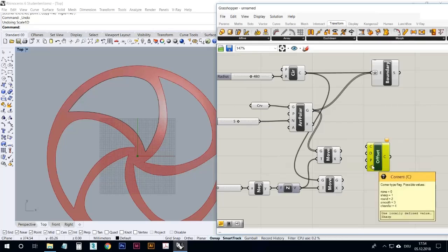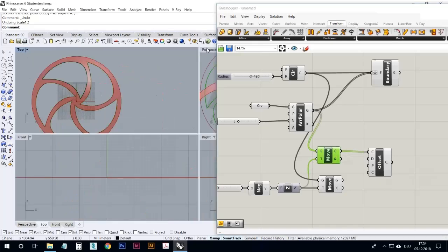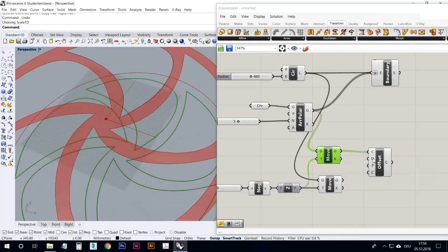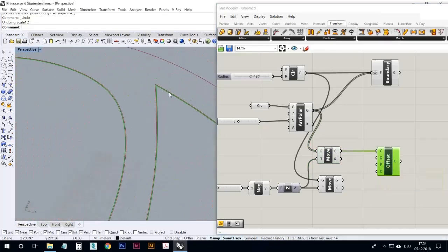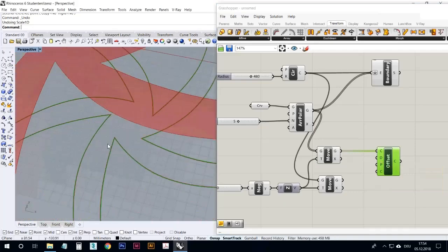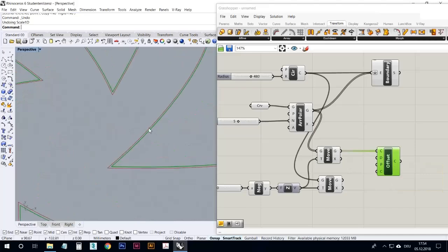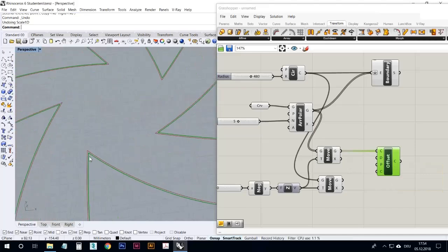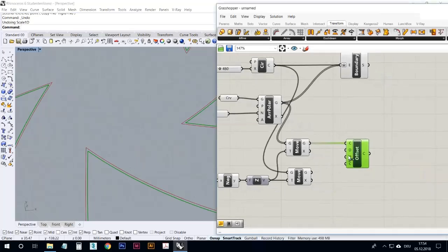And then we have different settings for corners of the curve, which is not really relevant right now. So if we take that one, I'm just going to check if that was the correct one. Yes, it was. So on default there is a setting that's actually 1. That's pretty good, because then you can zoom in and see what direction it is. If it's a positive number, it's usually going inwards, but this depends on how you drew the curve. So it's going inwards now, so I can use a positive number here. If this green line were outside, then I would have to use a negative number.